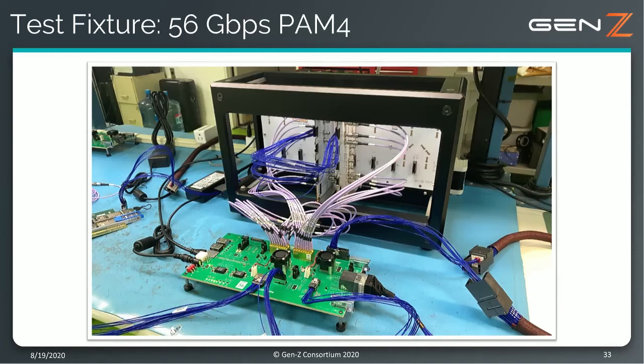The other 2 signals that went to the first riser card then travel through our Accelerate connector through about 14 inches of our twinax cable to the second riser card, where the signals go back. So we have 4 channels at PRBS 31, 56 gigabits per second PAM4 data running at the same time. And if we just switch now to the next screen, we'll see some of the test results that we got.